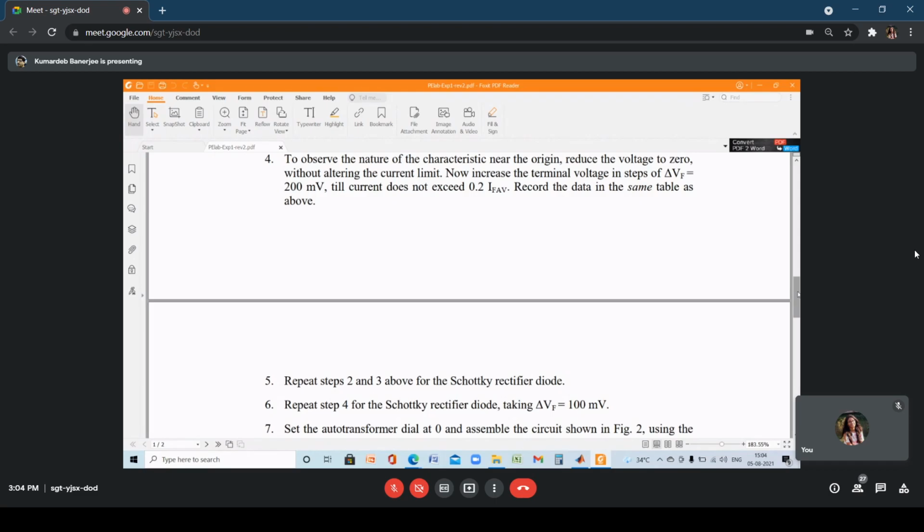So 0.8 volt is basically an indication that you have crossed from the first region where the diode voltage is less than V gamma to the second region where the diode voltage is greater than V gamma. So obviously we will not pick up 0.8 as a data point, but we'll pick up 0, 0.2, 0.4 and 0.6 as the 4 data points. And from these 4 data points, we'll once again put a straight line fit, right? If I mark them as section A and section B, then these 2 straight line fits, if extrapolated, will meet at some point. That is the cutting point.